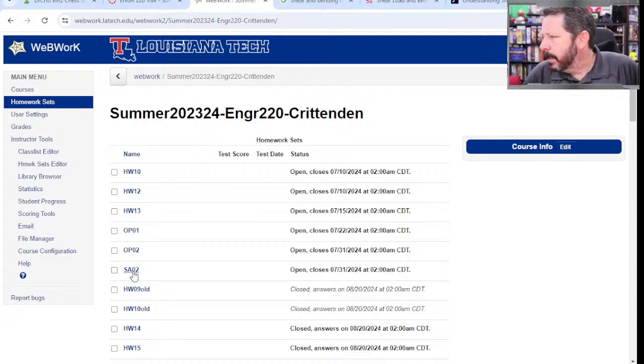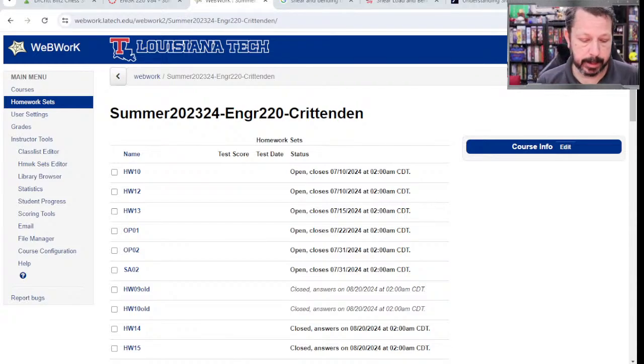The moment diagram is just treating the area of the V as a slope. The magnitude of the V. So the area of the V, like this 24.92, is the change in moment diagram. So the slope of this red line for the moment diagram is the magnitude of the shear.